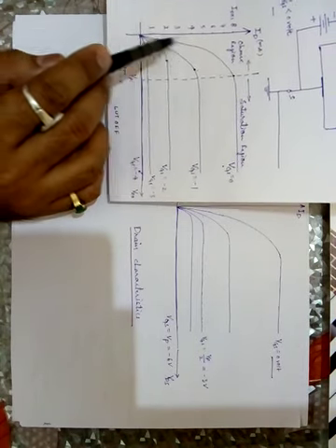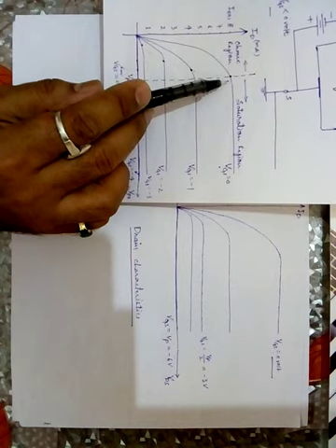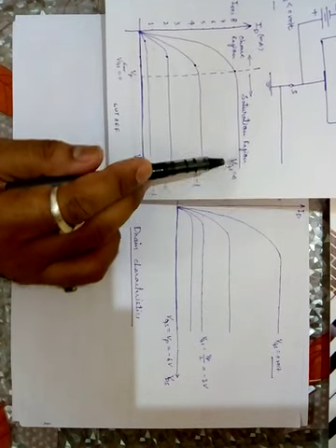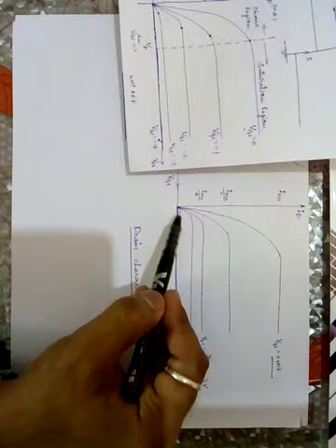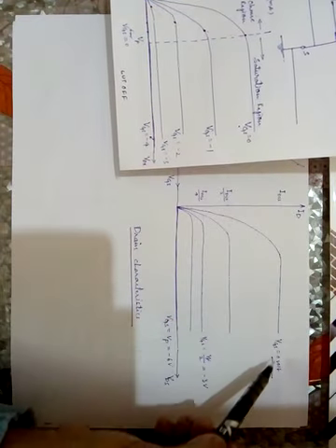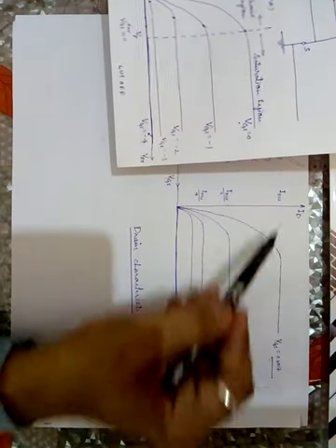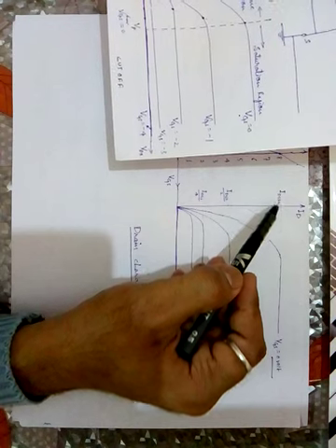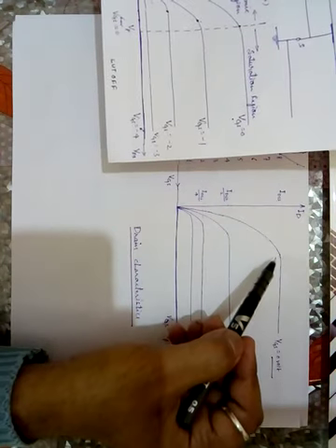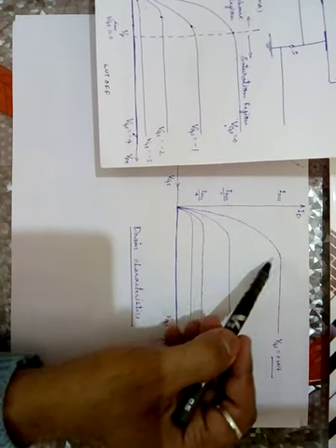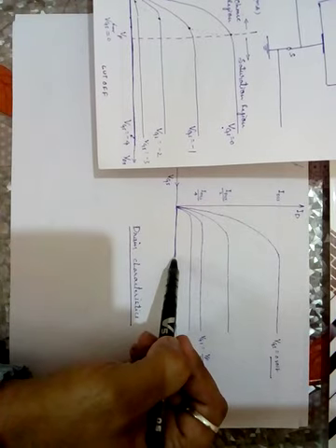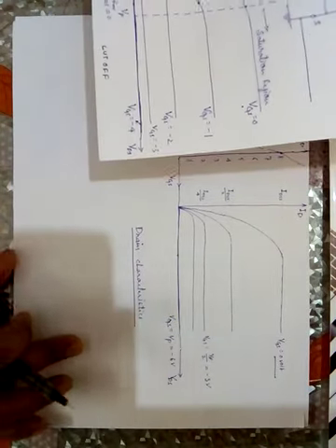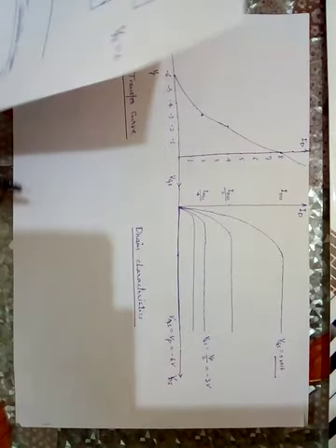The current is increasing up to a particular voltage, and after that the saturation region comes. The same is happening: I am increasing the VDS, and the drain current becomes constant after a particular voltage. And what is the amount of that voltage? Again, we don't call it a pinch off situation, but the same thing occurs here. I am just going to explain why it occurs.